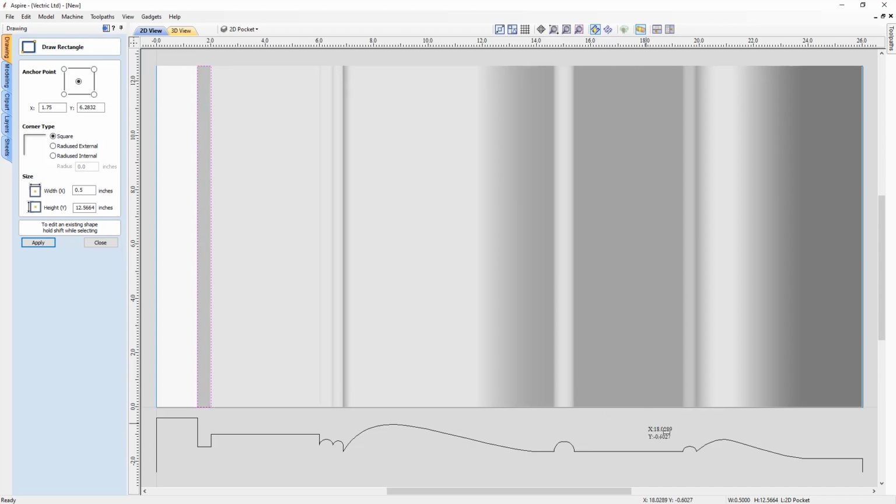So moving on over, you want to wake up this point here, and you can see I'm now snapped to the corner there, so I can click and then bring that up. Let's just wake this point up. By waking a point up, you just simply need to hover over it to activate that. You can see I've got that line to follow, which is very useful. We're now snapping to the top bounds of our job, so I can click and there's our vector there.